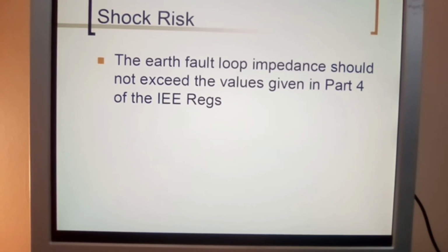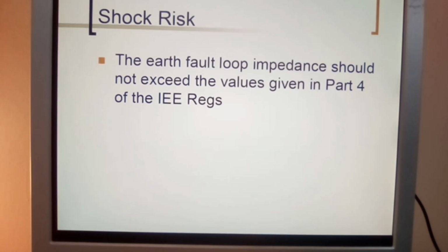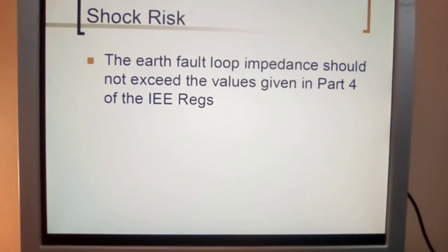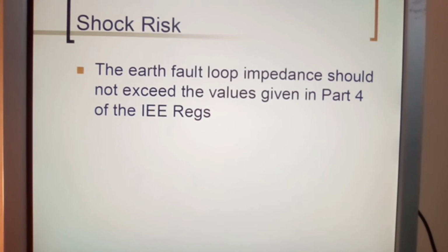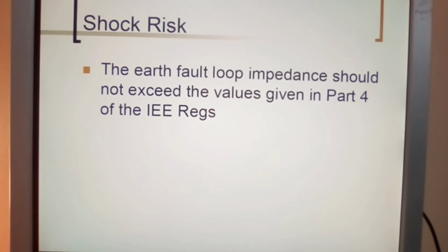Shock risk: the earth fault loop impedance should not exceed the values given in Part 4 of the IEE regs. Again, make sure you're compliant with the requirements of the IEE regulations in regards to shock protection.